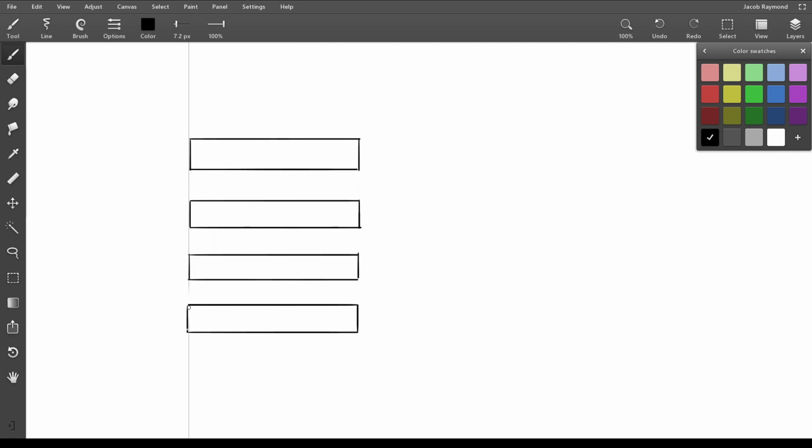So we want to be able to say, okay, provide some way to specify which of these locations we want to write to, and then we want to have one input D here that will write to a specific location. And D here is going to be 4 bits in this example, but it really doesn't matter. It could be n bits. So how could we possibly choose a location to write? Well, I've chosen 4 here because it's a power of 2. And as with most things that deal with architecture, anytime you deal with a power of 2, it's generally easier, and also likely has something to do with binary.